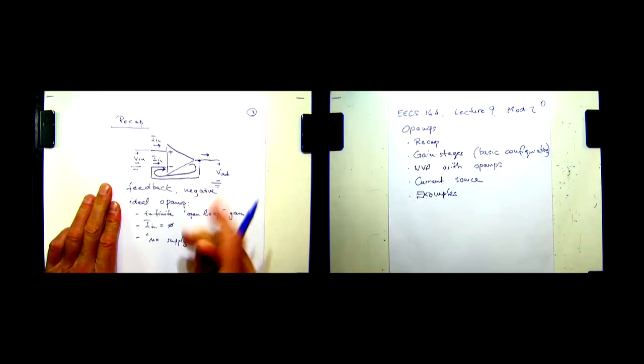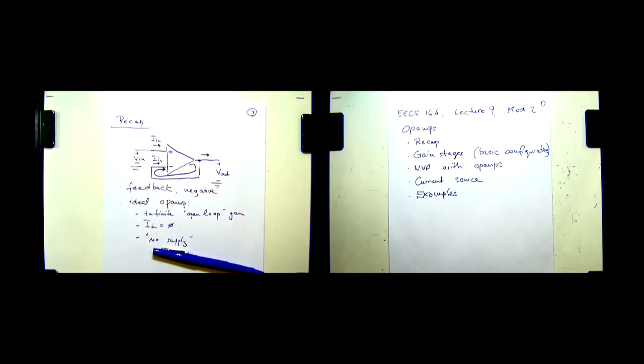So there is also another thing that we just have to be aware of. If we omit the supply, if we do not include the supply, then Kirchhoff's current law doesn't seem to apply for the operation amplifier. In other words, we get a current at the output, I_out, that is non-zero.